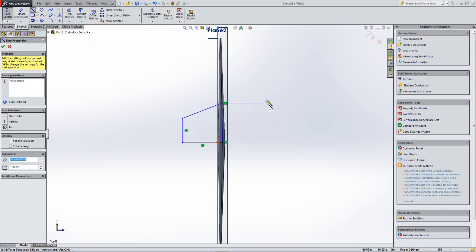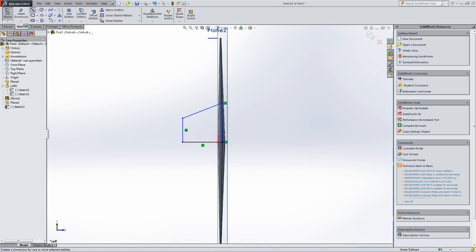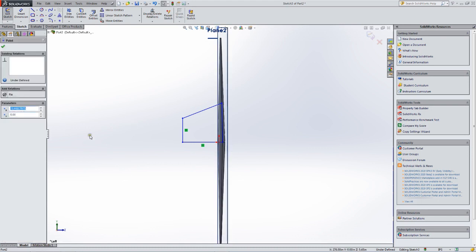I want to stop drawing lines. It's selected up here, so I hit escape, and that is my fuselage cross section. Now there's a couple of things. I want to mirror this to ensure that it has bilateral symmetry, and these little green locks for certain points sometimes are helpful. Most of the time I don't use them, so I just delete them. You highlight them, they turn blue, and then you hit the delete button. I want to make sure these points are at 0, and yes, that's at 0. It's parallel, so this one would be at 0 y coordinate.